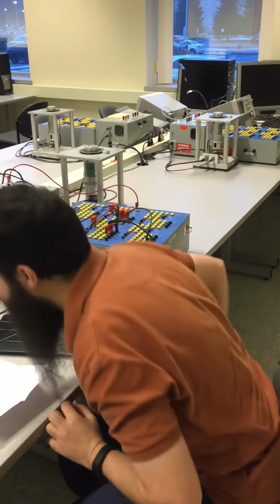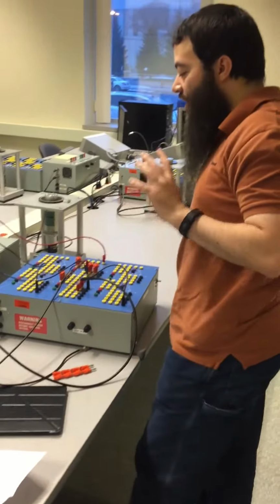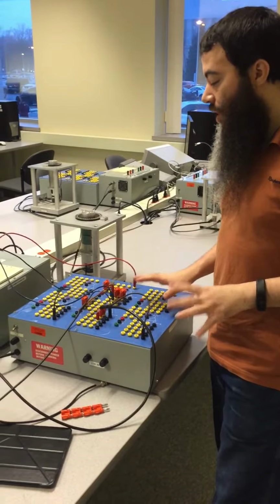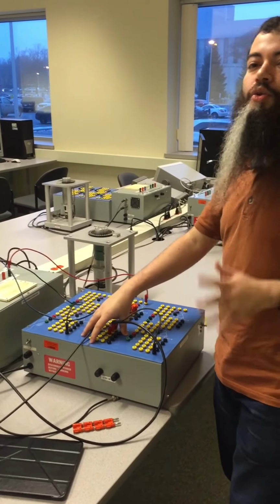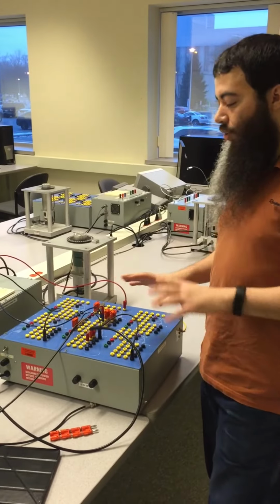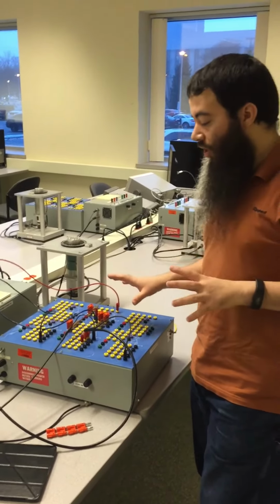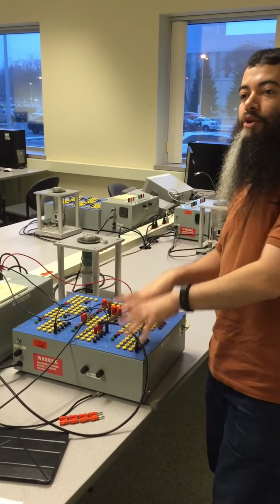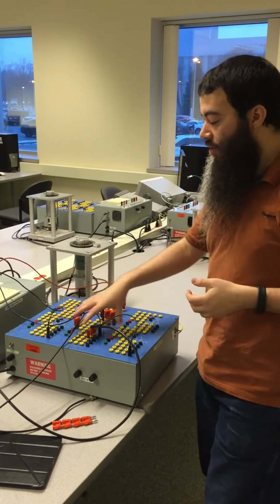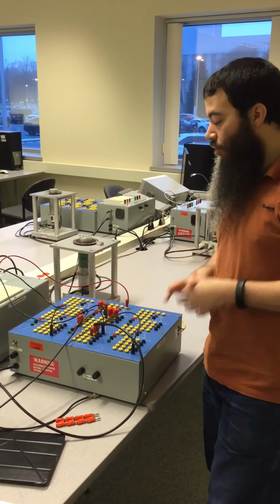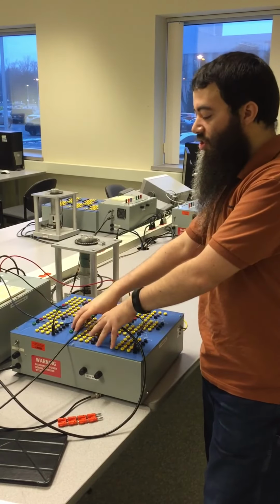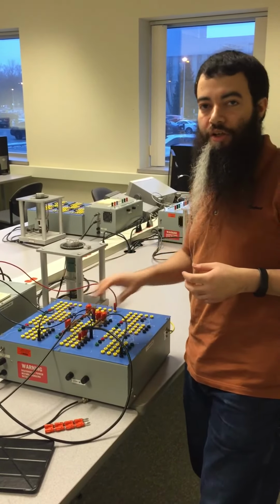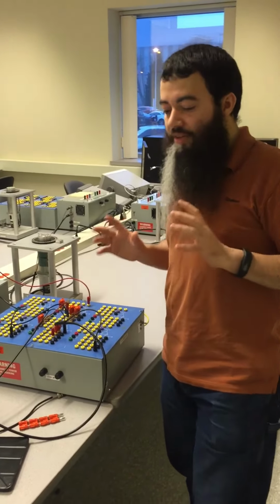Okay, in some cases, perhaps not in lab 2, but in some cases in lab 3 or lab 4, because of the excessive use of these control units by all students, one operational amplifier is not working. So for example, you connected the circuit, you think that everything is fine, but it's not working. What you can try is, instead of using this operational amplifier, you can try another one. Because sometimes it happens, because of the excessive use, some operational amplifier doesn't work. If that happens and you use another one and it worked, please tell me that there is some operational amplifier that is not functioning here, okay? This will not be so common, but it can happen, okay?